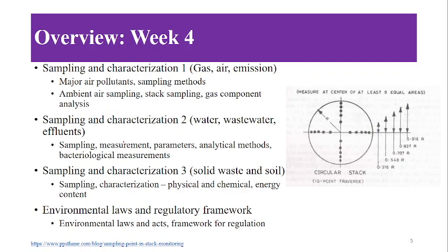Next, we now know how to measure the concentration using different instrumental analysis. However, how to sample the polluted air, or the polluted water, or polluted soil. In that, we discussed different sampling methods for air, water, and soil, and saw for air specifically the stack sampling, because this is the diagram for stack sampling for a circular stack, and we see at different positions we need to sample the flue gas which is passing through the stack.